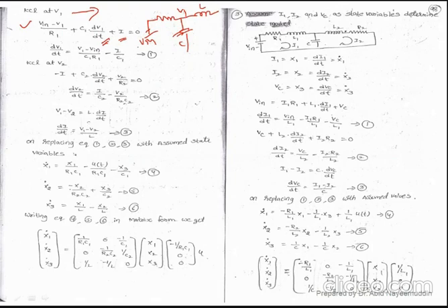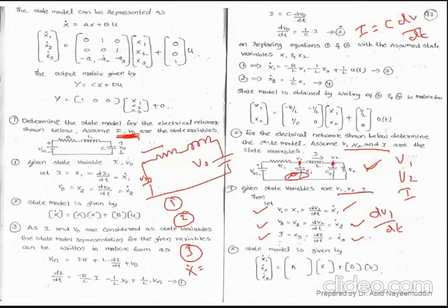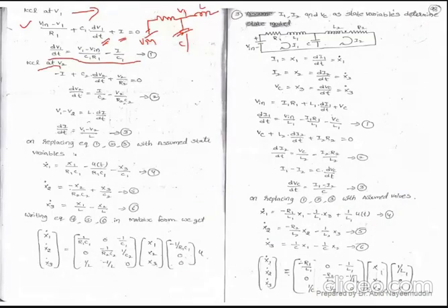From this expression, I can write directly dV1/dt is equal to (V1 minus Vin) by C1R minus I by C. Okay. Now in the same way, next applying KCL at node 2. In the given problem, this is your node 2, V2. At this particular node 2, capacitor C2 is connected.